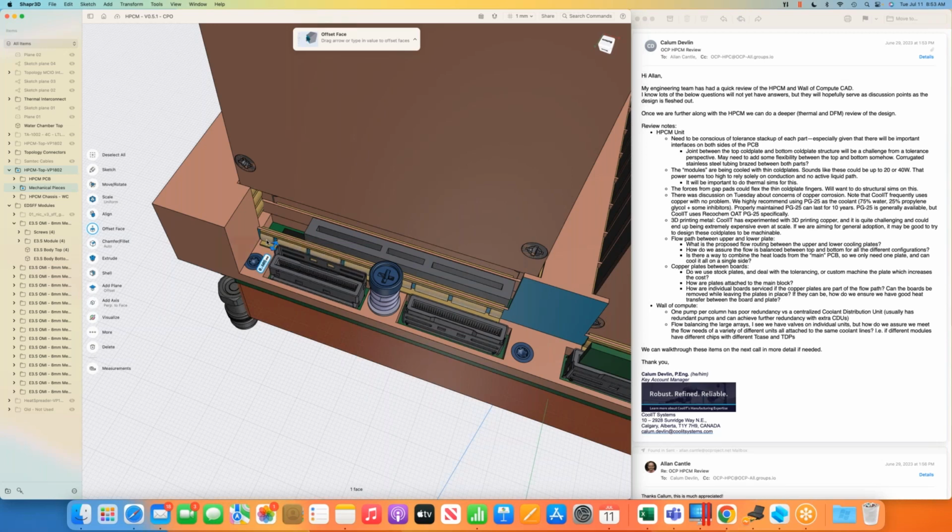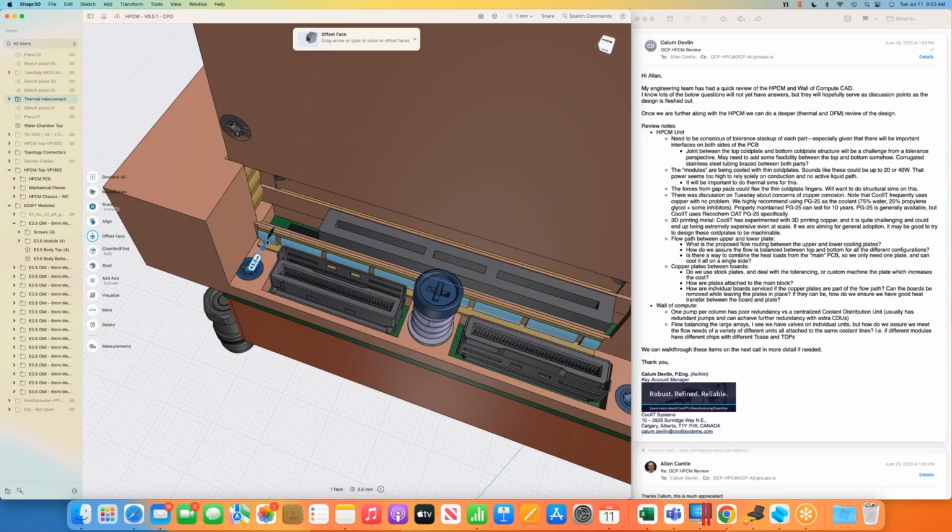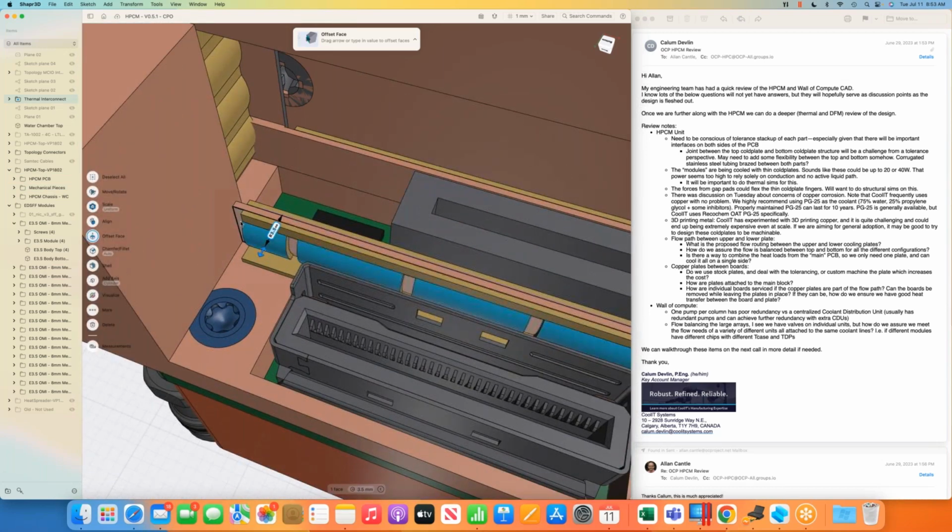The connector, this gold thing. Because I'm looking at the thermal path, if there's some sort of thermal material, you would have to ensure that you got sufficient compressive forces, or you're not going to get phonon transfer, so you're not going to get heat movement through there.